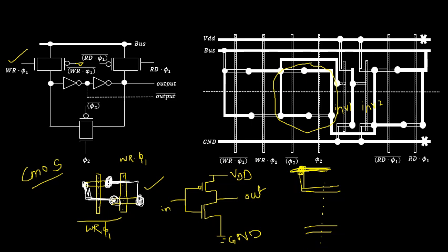So you are having a polysilicon layer vertical, that is the gate structure in this manner. So VDD connection will be applied through the source terminal of P MOSFET. Next I am having a metal layer used for the ground connection. Okay.